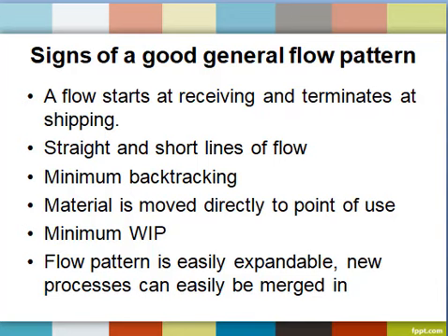There are signs of a good general flow pattern. A flow starts at receiving and terminates at shipping. Straight and short line of flow. Minimum backtracking. Material is moved directly to the point of use. Minimum work in process. Flow pattern is easily expandable. New processes can easily be merged in.